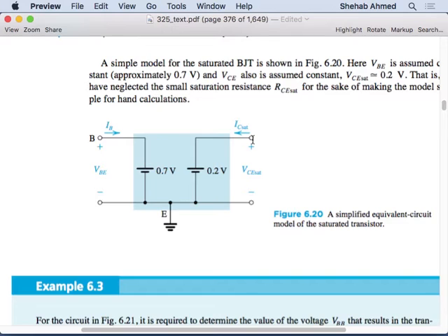In power, in very high voltage devices where you're trying to operate in saturation mode, you're not going to try to put resistors in series with the device. You will have your motor windings. You will have the filter inductance. You will have your power currents. You will not try to add more resistances there. In the active region of operation, that's where you want to put these resistors to try to fine tune where you're going to operate. And why is that important? That's what we're going to see next.